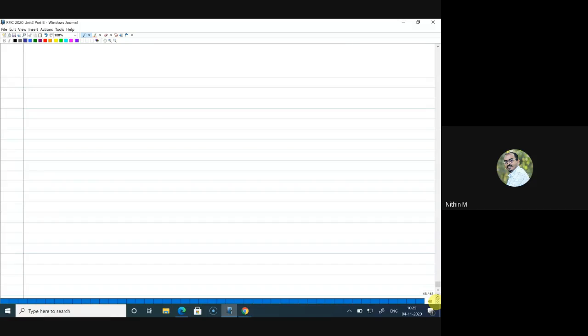from C and D, those components will be eliminated, and I can write what is x e of t and x f of t. So what is x e of t? X e of t is a signal by 4 cos of omega c minus omega 1 minus omega 2 into t plus a image by 4 cos of omega im minus omega 1 plus omega 2 into t. So this is x e of t.